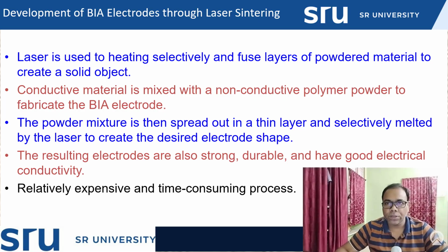In this process, first the powder material is spread on the build platform, and then only in the areas where scanning or printing is required does the laser pass, and then fusion and binding of the SLS material takes place, and then one can go for the finalization layer upon layer.